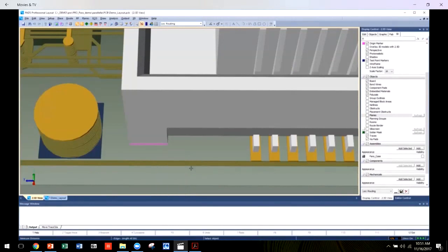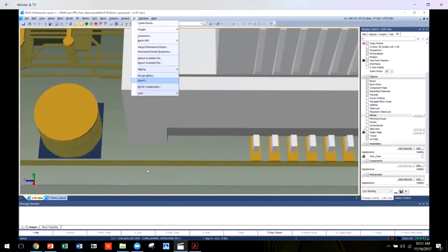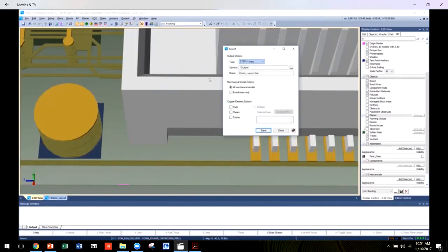Double-check connector placement in regards to the assembly and component offset from the board edge. By simply clicking once on the object of interest, the measurement tool automatically snaps to other objects when moving the cursor. Remember, you're checking the design before the PCB is sent out for prototyping, allowing for extra passes of verification. The purpose of all this is to minimize rework by catching placement or part choice problems earlier in the design cycle. Also, present your board outline with its 3D representation with 3D PDF, or export the entire board as a STEP model.